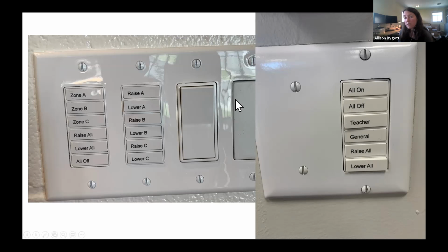And the problem with different brands of lighting control systems is trying to coordinate how many junction boxes you need, how many switches you'll have, how many buttons you'll have. And that's why some of these are cover plated over, because the design strategy changed between the contract documents and the shop drawings. And so it affected how many boxes you needed and how many buttons would be on each switch. So it's something to think about.